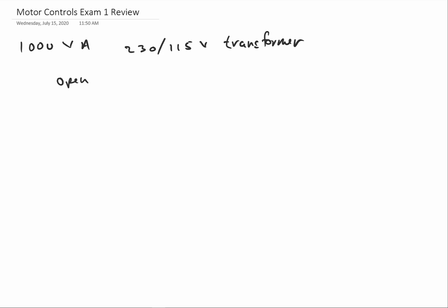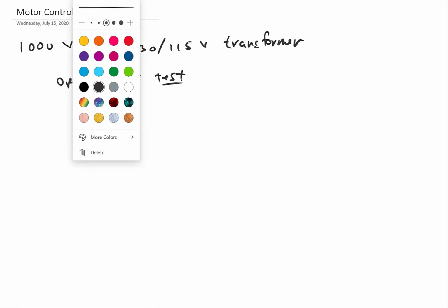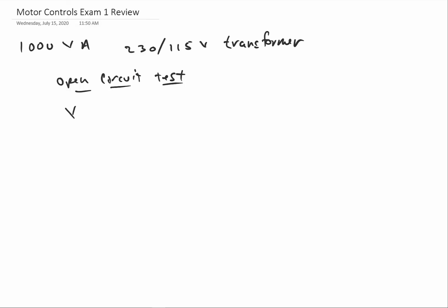For the open circuit test, the open circuit voltage was 115 volts. The current was 0.11 amps. And the power was 3.9 watts.